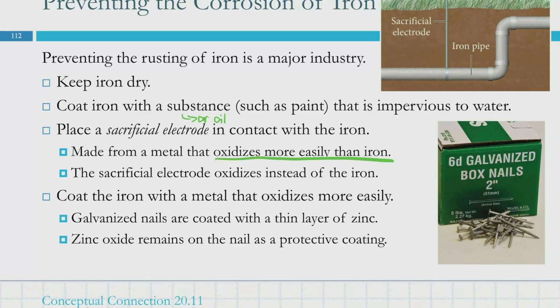And to keep them from rusting and from degrading and falling apart, they basically just screw on big electrodes that are going to rust preferentially to iron, and they just swap those out every now and then. And it's a lot cheaper because they're able to use cheap building materials. Iron's very cheap, it's all over the place. And by using sacrificial electrodes, they're protecting that iron from corroding. So I think that's cool.